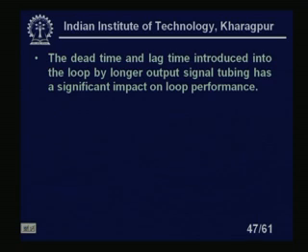The dead time and lag time introduced into the loop by longer output signal tubing has a significant impact on the loop performance, because whenever we are using tubing in pneumatic systems, it is not very predominant in the case of an electrical system, but in a pneumatic system we are using more tubing. Obviously, it will increase the lag in the system as well as the dead time in the system.